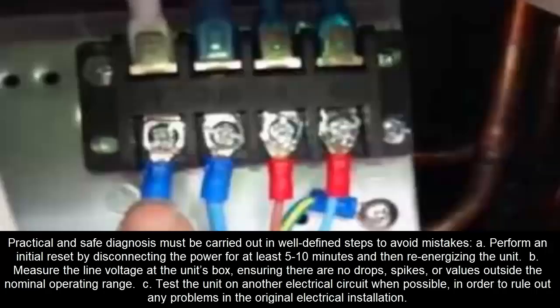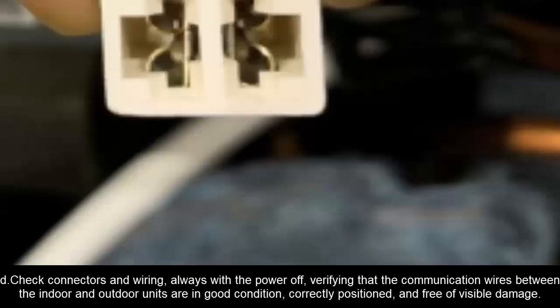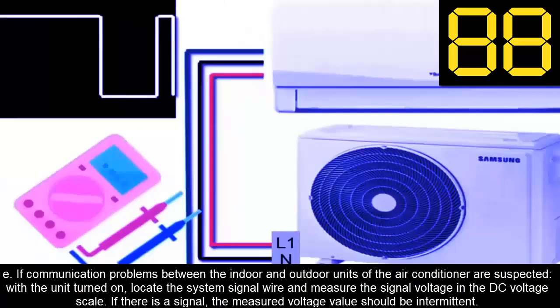C. Test the unit on another electrical circuit when possible, in order to rule out any problems in the original electrical installation. D. Check connectors and wiring, always with the power off, verifying that the communication wires between the indoor and outdoor units are in good condition, correctly positioned, and free of visible damage.